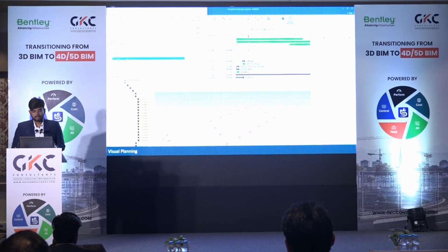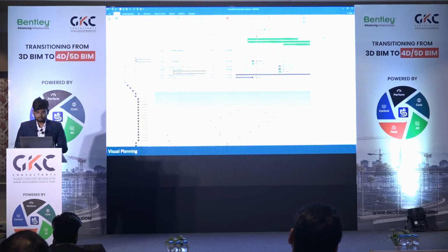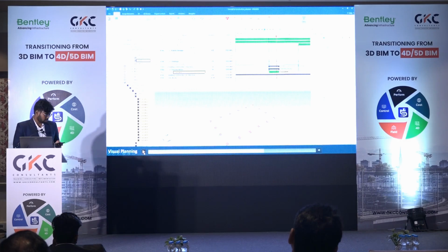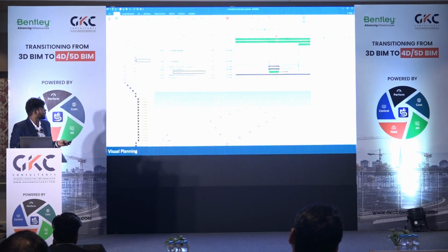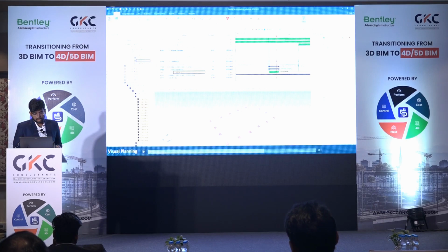So what do we mean by that? Let me show you. Here we have added a new task, and let me just pause it up here. You see that we have also added the logical relationship. You can also control whether it's finish to start, start to finish, what the logical relationship is. And we start reviewing how our plan actually looks like. So this is how it looks.